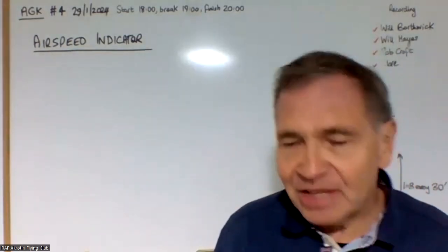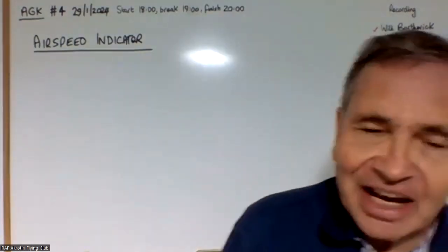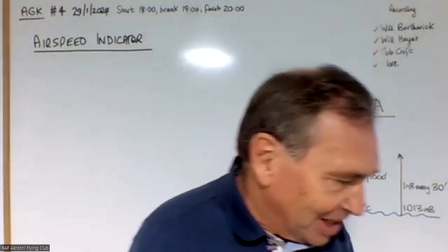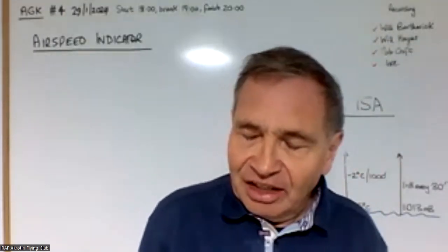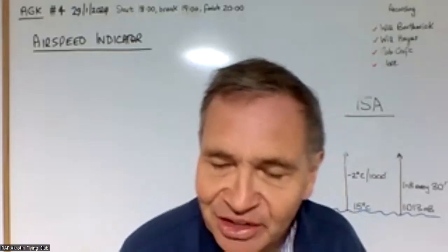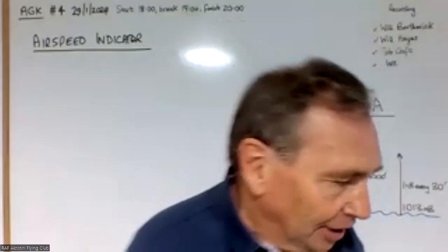Yeah, taxi back to the flying club. Investigate why your airspeed indicator's not working. And of course, the reason the airspeed's not indicating is because it's either blocked or it's iced up or something.